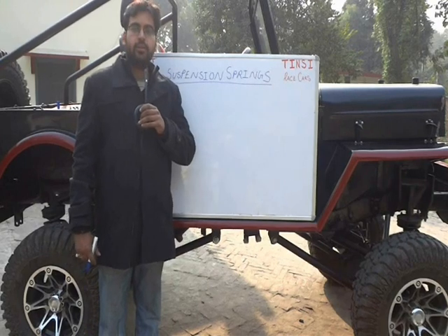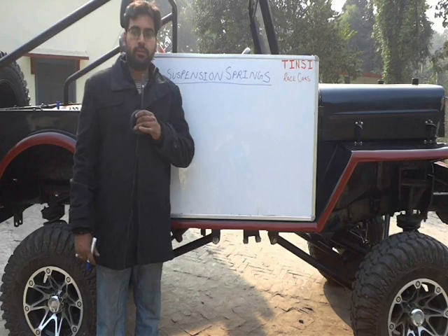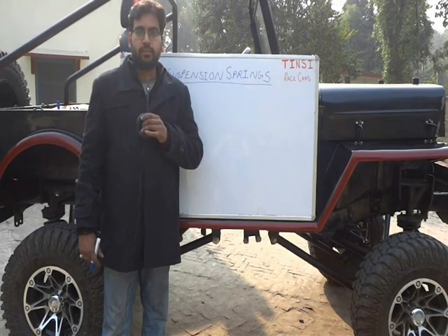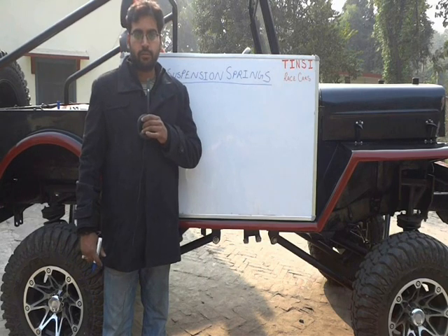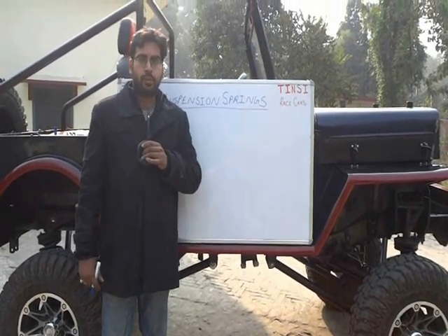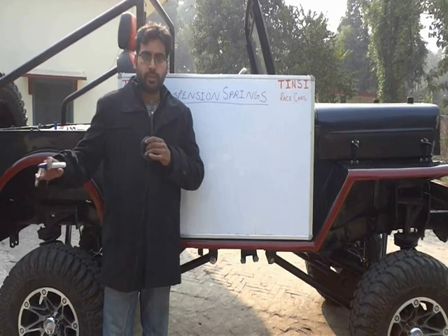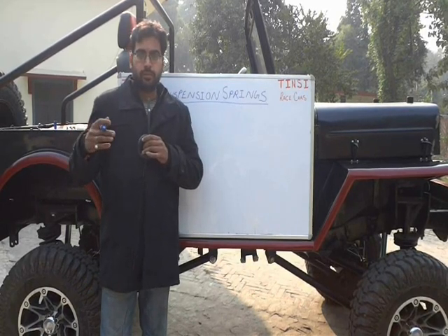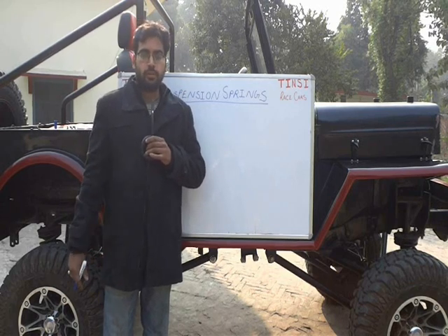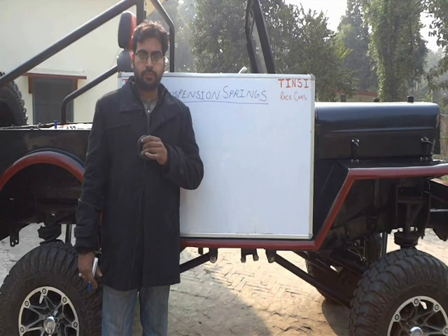So good morning friends. A lot of queries come to us about the design process that goes into the springs. It's not just the stresses and the number of coils and the diameter that you finally calculate. It's the complete process that goes into it, starting from the very basic, the weight of the vehicle, then all the dimensions come into it, the track, the wheelbase, the roll axis, the roll center heights, everything goes into it. So today we are going to take an overview of this design process.